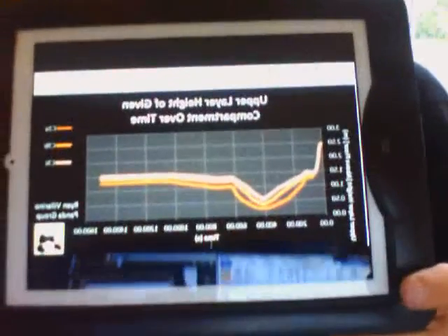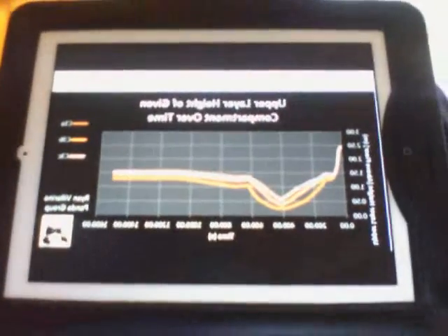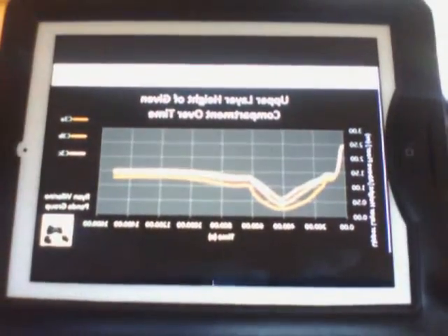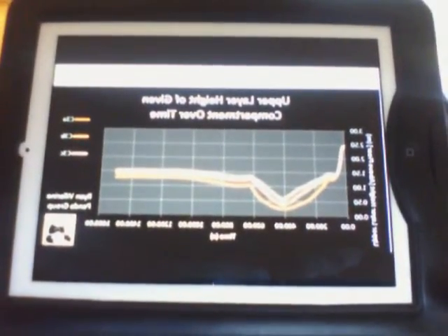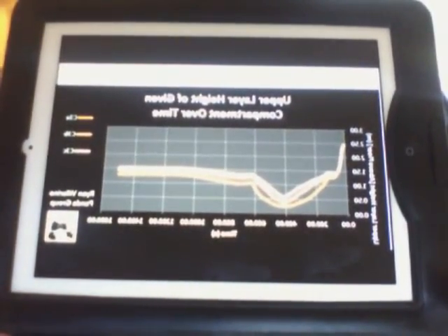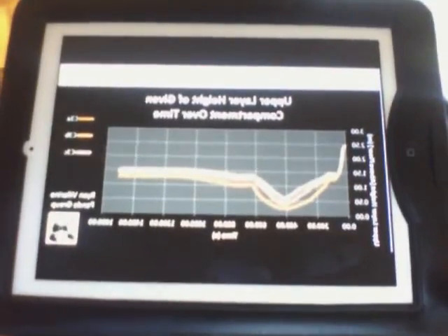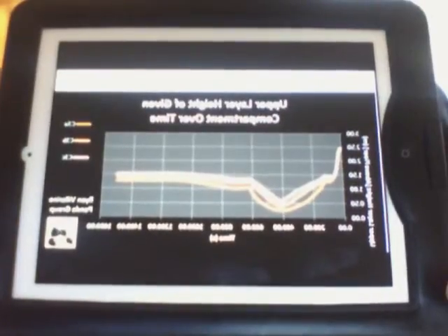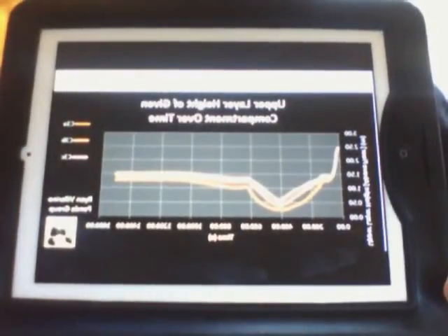So any sort of obstruction led to a higher temperature in there. And it also, as you can see on this graph, without the obstructions, that top line that you see there is C3C. So C3C with no obstructions gave a higher height, I guess you could put it. So the smoke layer would drop down less than it would in the other ventilation scenarios where there was a hallway.